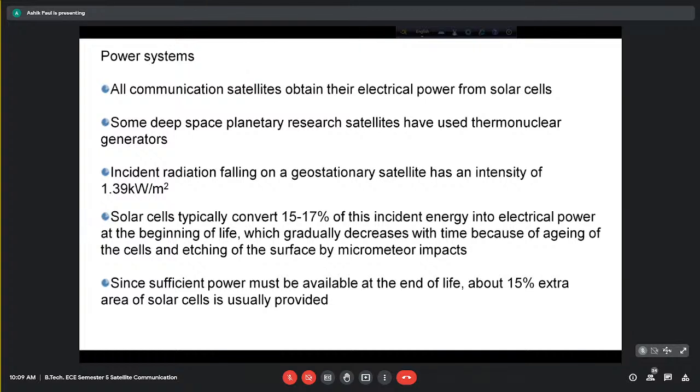And then, because we know about the location of the stable points at geostationary orbits, they are located, we have seen, around 75 degree east and around 165 degree east, the two stable points. All the geostationary satellites in orbit have to be parked near these points at the end of their lifetime so that they remain confined to those locations.